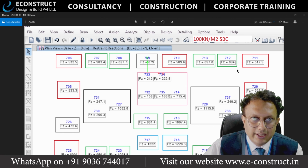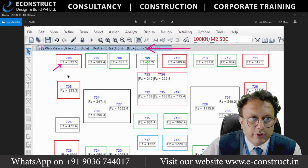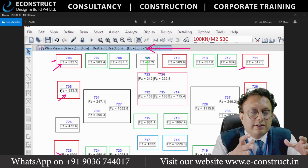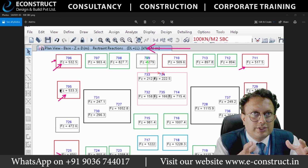What I have done here is grouping. What is this? Grouping, in the sense of how much is the dead load FZ value in terms of kilonewton. Okay. So first group 532.5, 533. I have taken up to 600. Whatever the figures are, they are in the same group. You can see that this is red in color. Why? Because the same amount of shuttering material will be given. I mean the same box.